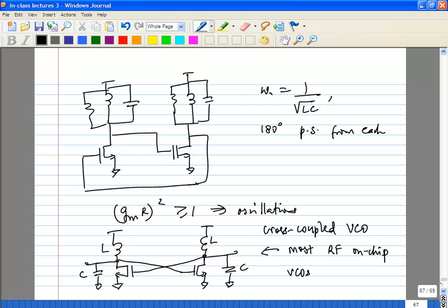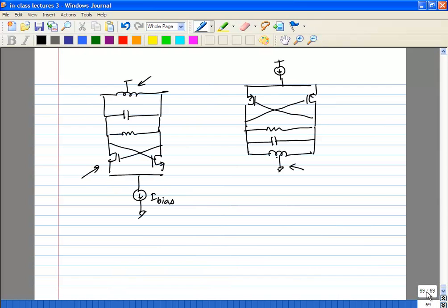I just made them a single inductor because we are going to compare it with a slightly different architecture, and you want to compare it with the same size of the inductor. That's why I did. We call that the center tap. So this is one full inductor. What you need to find is a symmetrical point such that the inductance is equal on both sides, like everything is equal on both sides. That's called a center tap. So you need to find something like that and use it here.